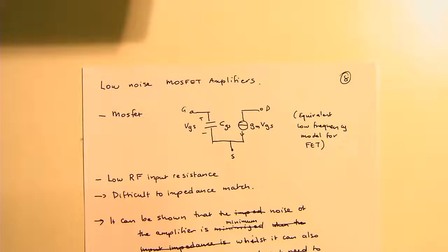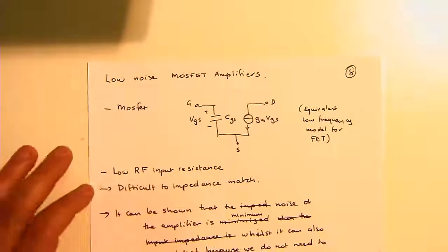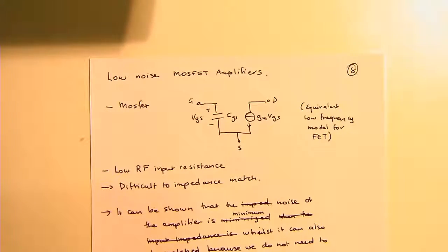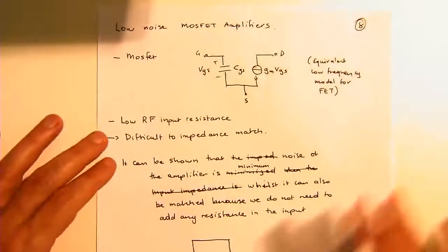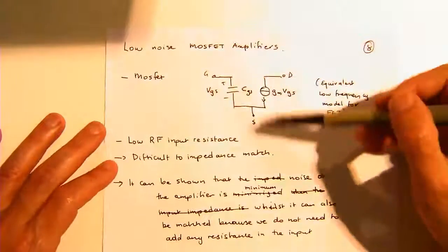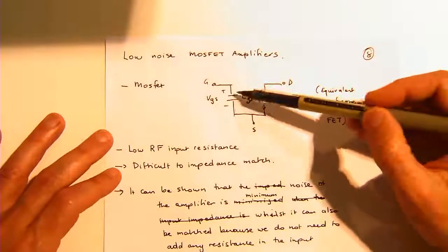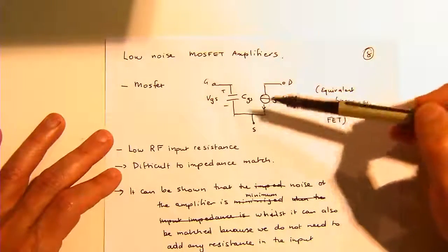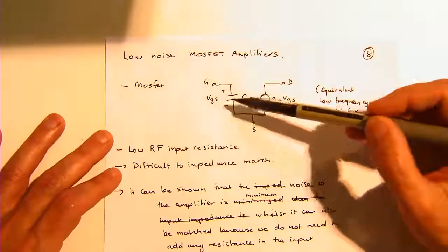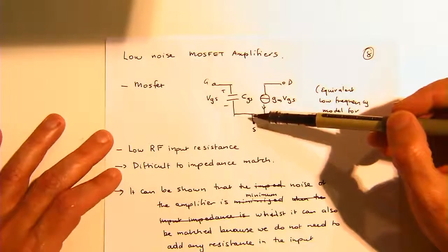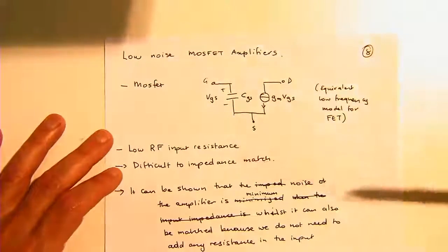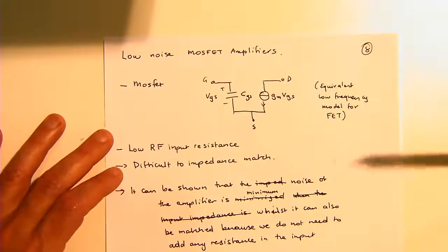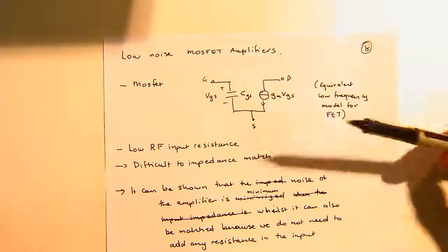Yes, channel length modulation. All right, good. Now, what we're doing here is, when you look at this, because it's purely capacitive, in most cases it's really hard to match. So when you're trying to do your standard scattering parameter design approach, it can be a little bit difficult.